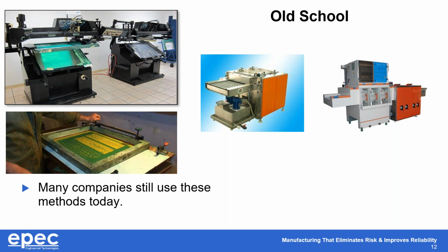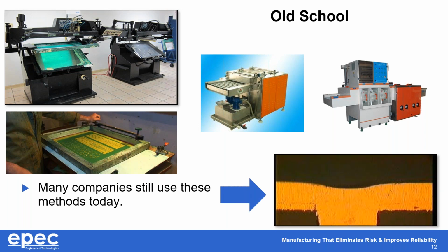So it really shouldn't be used in this process, because if you use the screen printing process to try to fill the vias, in many instances you end up with a feature that looks like this, right? And as everybody knows who has ever tried to solder a BGA, when you've got via pads that look like this, it becomes very difficult to make it solderable, right? And you create major challenges. That's not the flat top that you want.